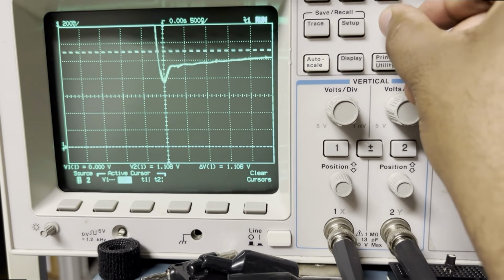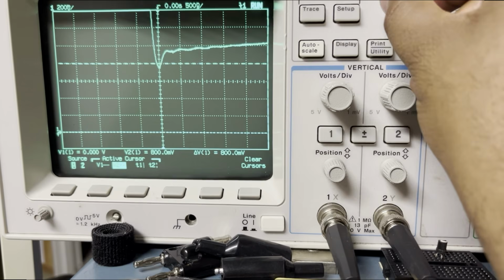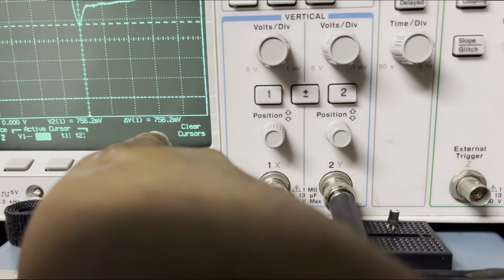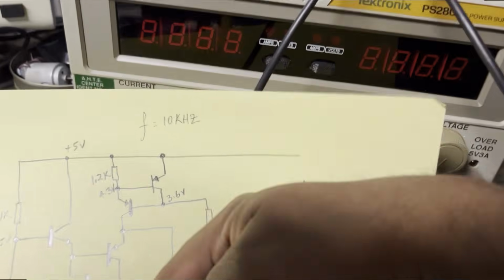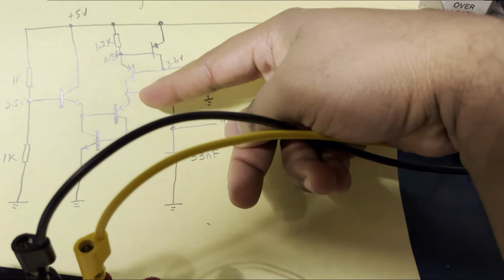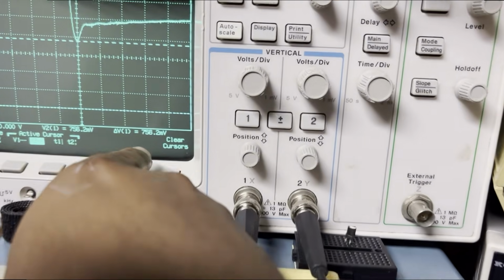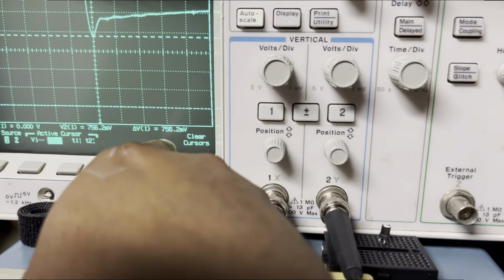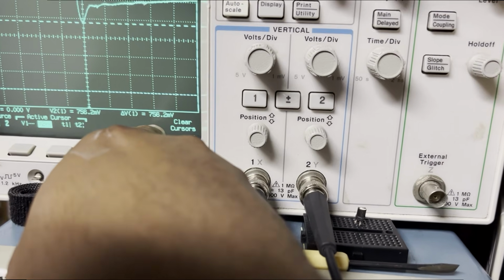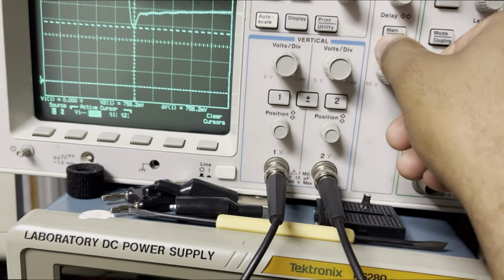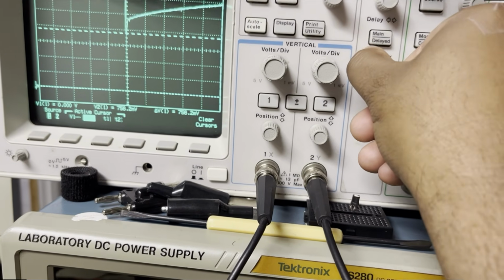At the bottom of that waveform, the capacitor is being discharged to a delta of 756 millivolts, right? We assumed it was about a VBE drop plus a VBE drop plus a saturation voltage here, which was approximately 0.8, right? But the circuit actually does slightly better, so it's discharging to slightly less than 0.8. There's a little bit of discrepancy from when we did our calculation, but good enough. It gives us a ballpark calculation.